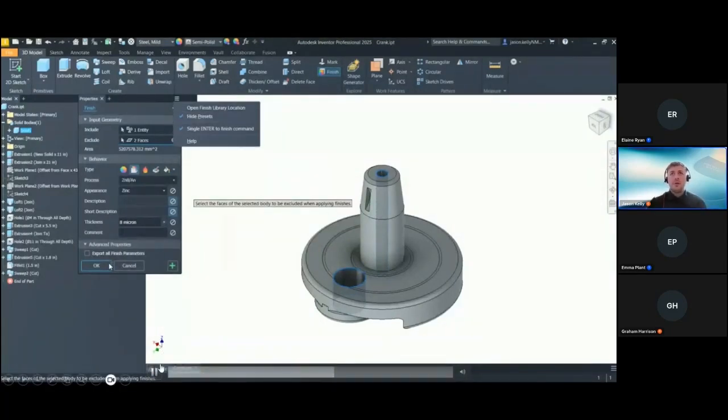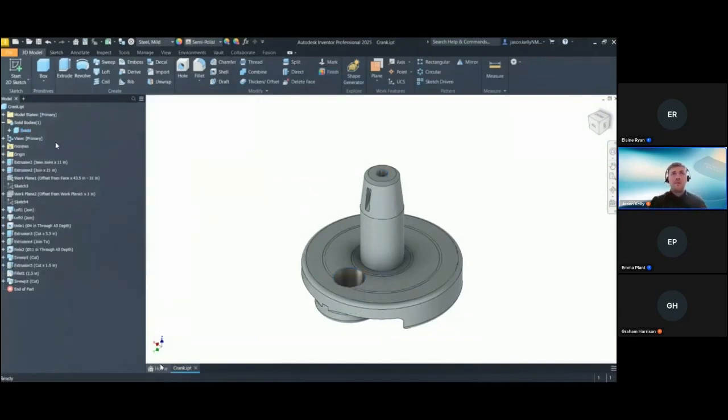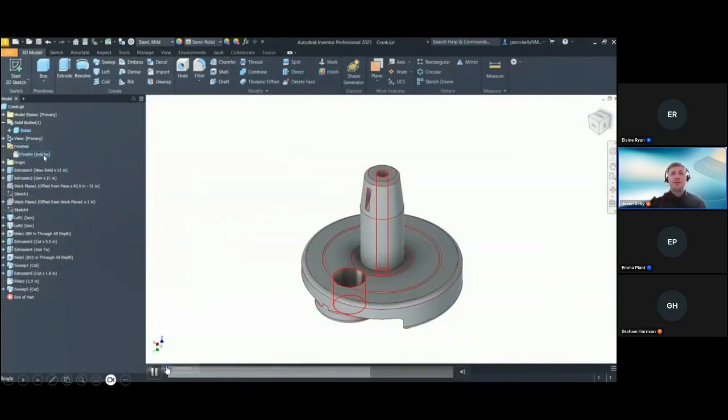One of the other functions they've added, once you've completed the command, is you can now show extended names. If you're not aware, show extended names will give you more detail about the particular command you're in. For example, if you're creating your extrusions and your lofts, you'll see if you go to this little three lines menu, you've got a display preferences option and you can turn on show extended names. That's something I'd recommend to everyone. But now, rather than it just saying finish 1, finish 2, finish 3, you can actually see what finish has been applied, and as you hover over it, it highlights the faces, with the faces that aren't turned on not highlighted.